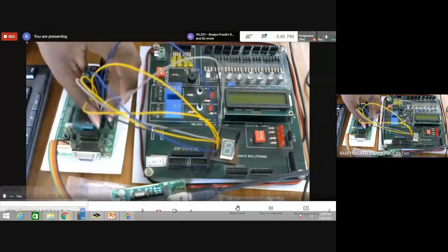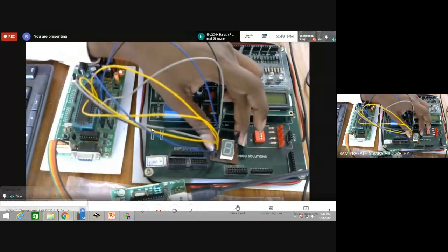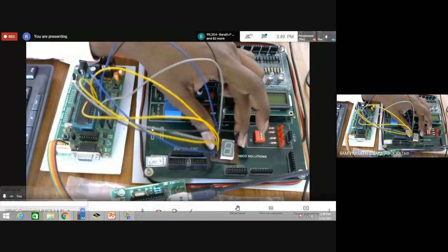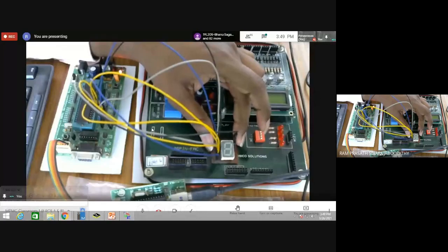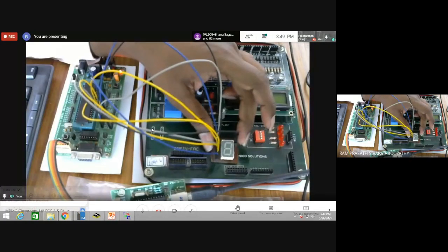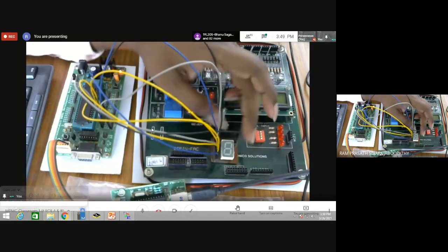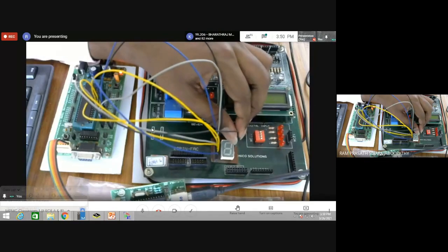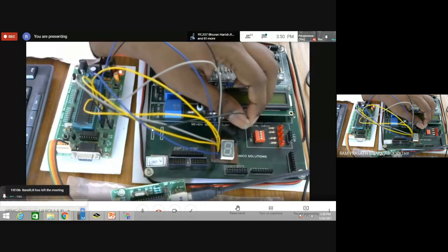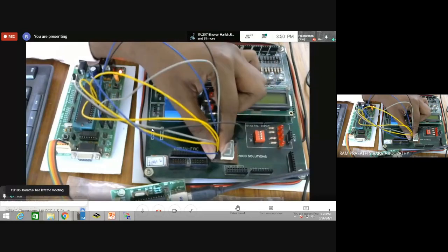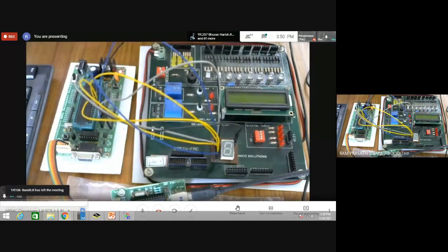That's all. See, regarding this particular IO board, the 7 segment LED alone is independent, so there is no need to give power separately. Fine. Every connection is given. The anode pin of the 7 segment LED is connected to plus 5 volt. All other remaining segment pins are connected to port 2. Fine. Shall we burn the code? Yes. Yes or no?